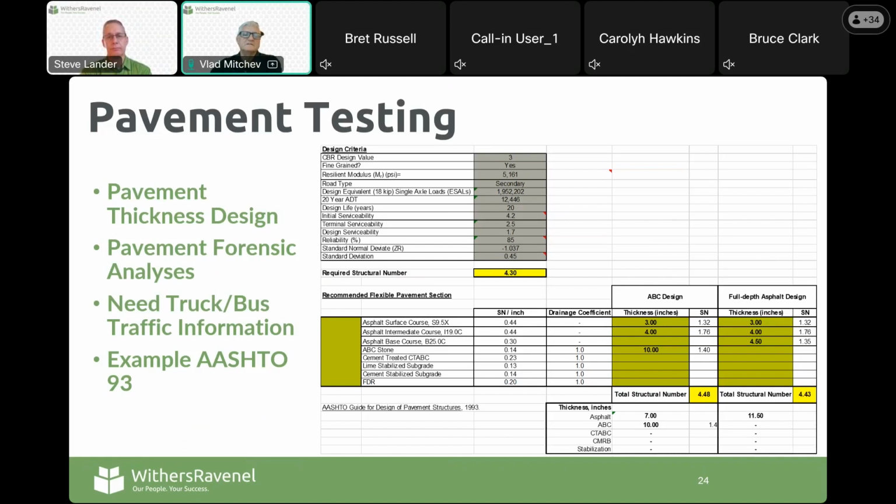In order to do pavement design, there's a little bit more information needed, such as traffic, mainly the truck roads or bus roads, and then you can conduct different kinds of analysis for different durations and use even the existing information for the pavement thickness with the coefficients of original structural coefficient, by depreciating them to current condition and adding the needed structural coefficient to achieve the required structural design life.